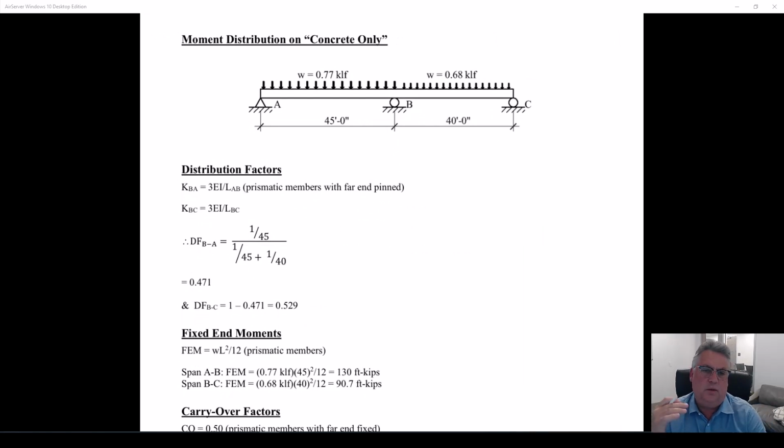So I can't impress upon you enough that this is the concrete only. This isn't statics. Just like we did in the simply supported beam, we took out the tendon diagram. That's hovering off to the side. Remember that the upward loads that the tendon's creating on the concrete are equally and oppositely balanced by the concrete pushing down on the tendons. So they really offset each other. That's the correct static approach to this. This would be the 2.0 kips per foot. That's statically correct. If you did that moment distribution, reaction, shear diagram, that's what statics says is happening.